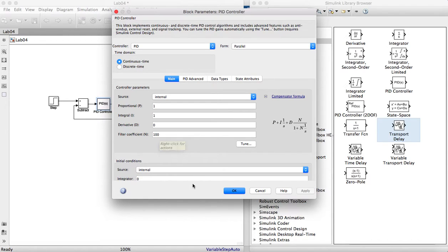The next important thing that we note is that while we are able to input our controller parameters directly, Simulink has access to the MATLAB workspace. So by writing a script in MATLAB, Simulink would also have access to that information. For now, we will define everything by parameters as variables. Instead of inputting numbers for proportional, integral, and derivative, we just put a variable, and then later we will define it in MATLAB.